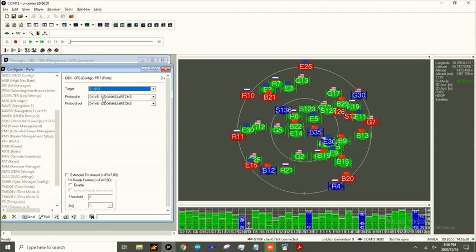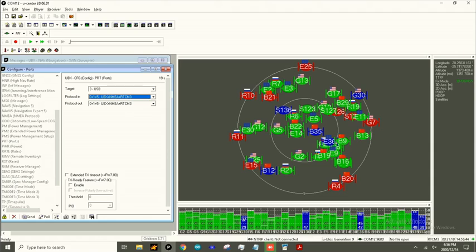And then you will see that it's 0+1+5 for UBX, NMEA, and then our RTCM3 correction messages that are required. So that's the selection for both the protocol in and out, but that is also set by default. Once this is done, you should see here on the right hand side that we see the fixed mode is